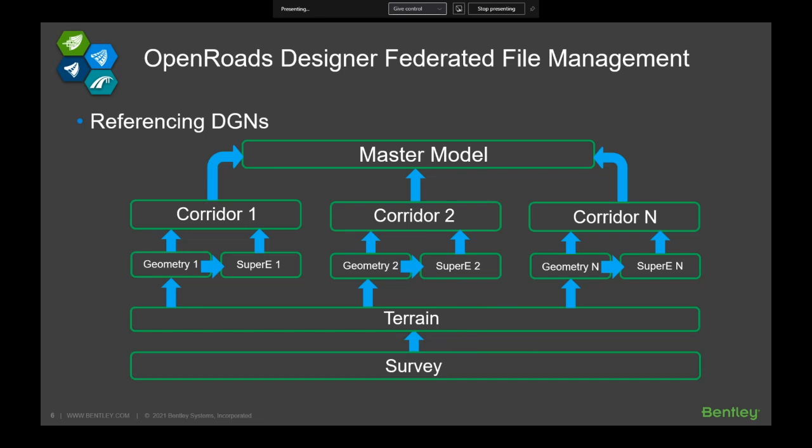Okay, if the word seems a bit big or something, so just create every object. Okay, it could be that depending on the size of your project, it could probably be a best practice to create each of the major geometries in different DGNs. Then just reference the common terrain file that you have created.